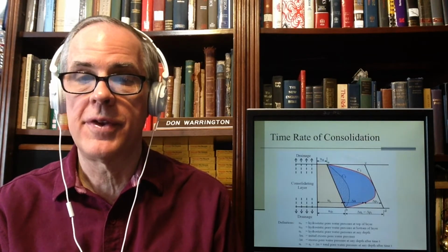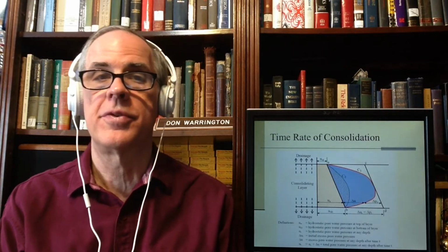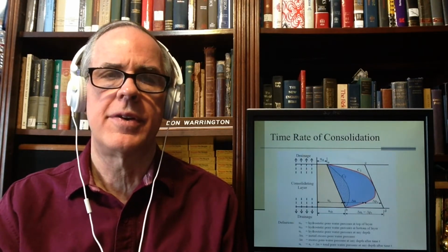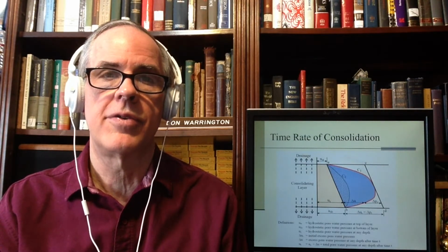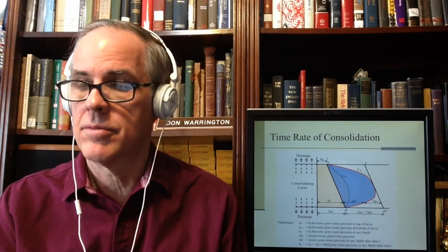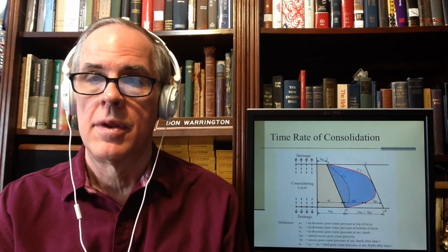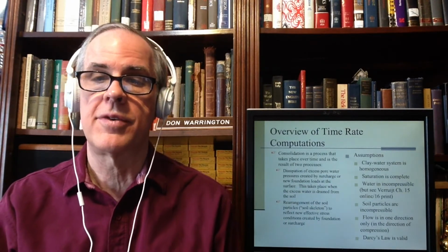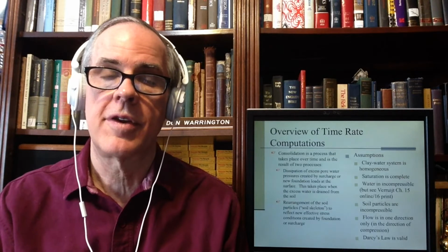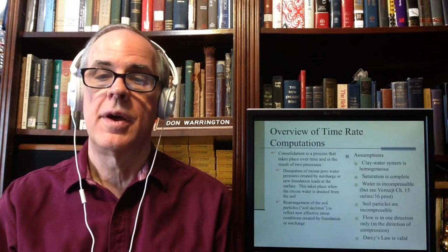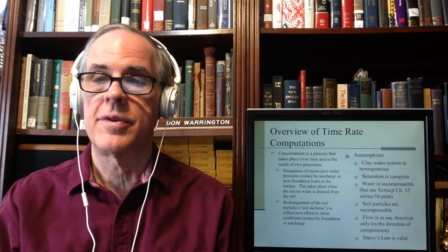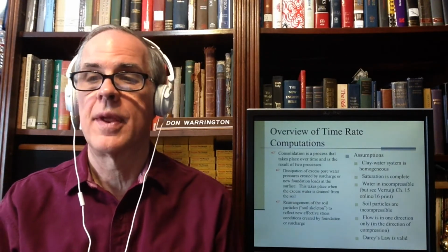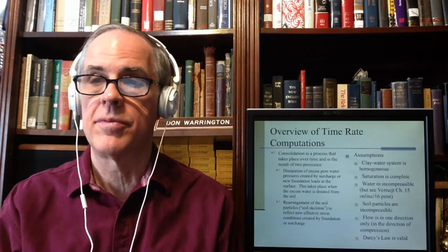And I've got some definitions there. This is also from your Soils and Foundations handbook. They do a fairly decent job of presenting consolidation and settlement. Consolidation is a process that takes place over time, resulting from two processes: the dissipation of the excess pore water pressures and the rearrangement of the soil skeleton. There are some assumptions, and I'm going to discuss both of those.